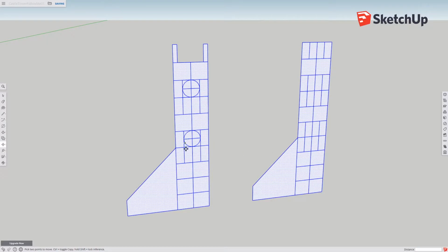But let's have a look here. Now I've drawn these two little circles because I want an archway in my door. The beauty of breaking it up into 1 meter by 1.5 meters and 2 meters there is I've got little 1 meter squares really. So I'm going to change it to a circle. Now I'm not going to change a circle to be anything more than the default, which is a 24-sided polygon like that. And then I'm going to go through and delete a few things.